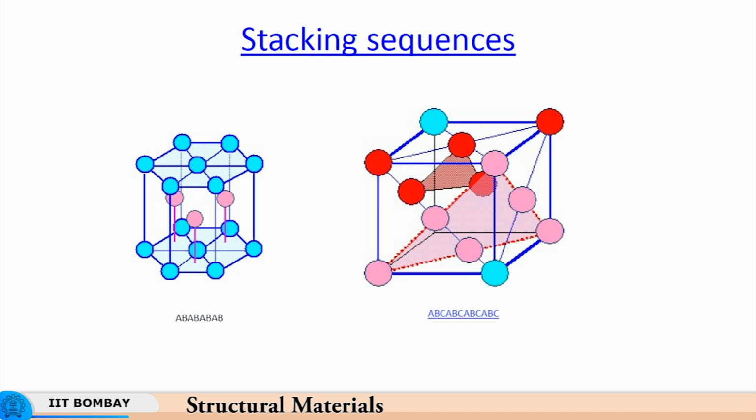These defects accumulate, and then they undergo either so-called dynamic recovery, which means that subgrain boundaries are formed as a result of an excessively high amount of dislocations getting piled up, or the material recrystallizes, meaning the stored energy of cold work is dissipated in generating new crystals. Now, what will happen in which material is governed by the so-called stacking fault energy, meaning the energy that is needed to generate a stacking fault.